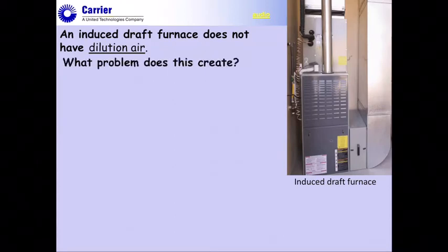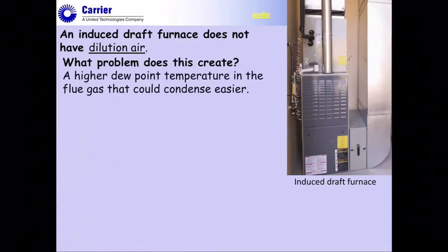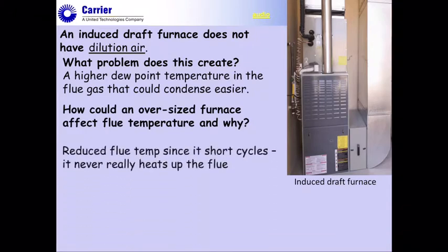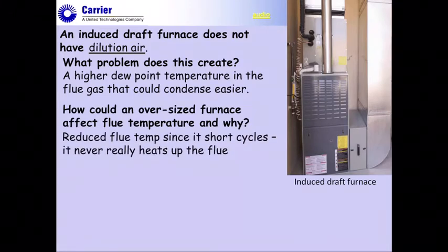So, since an induced draft does not have any dilution air, what problems does this create? Well, the higher dew point temperature in the gases without the dilution air means you're going to condense a lot sooner. So the question I ask you is, how does an oversized vent system or an oversized furnace affect the flue temperature, and why? The way I have looked at this is reduced flue temps, because it's a higher efficiency system and you don't have the dilution air.